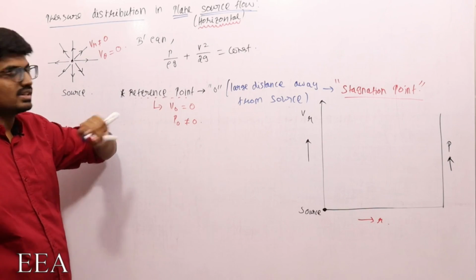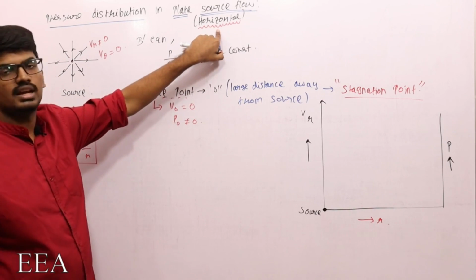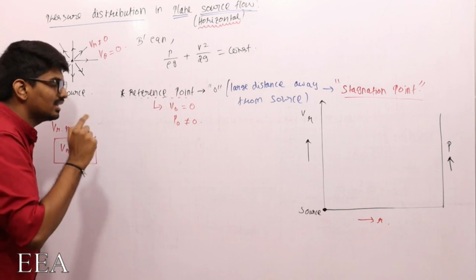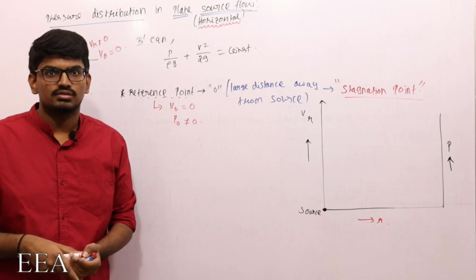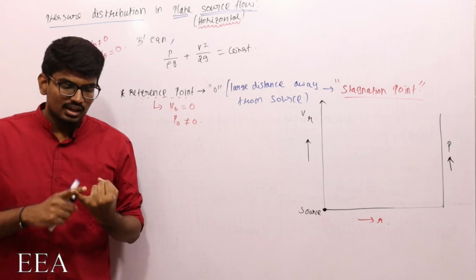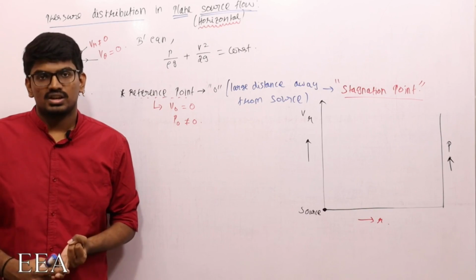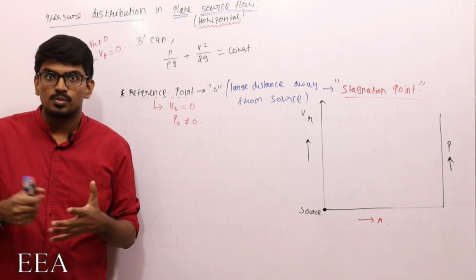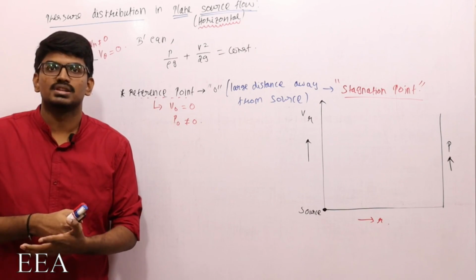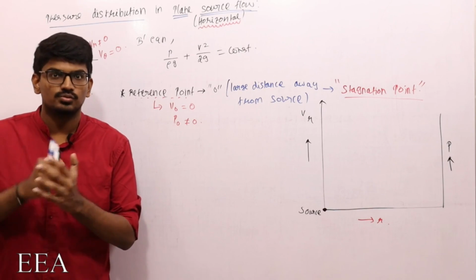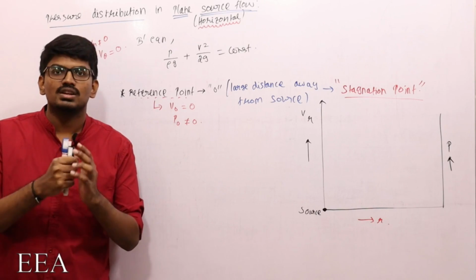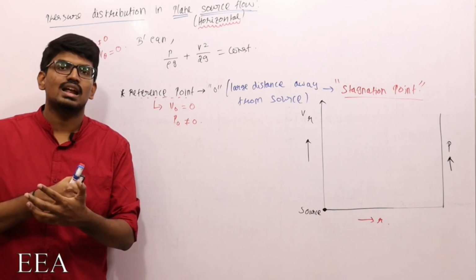Now, this is our general Bernoulli's equation. I'm not considering the potential energy because it's horizontal, and the potential energy will remain the same along a horizontal line. We also know that it is an irrotational flow. Why is it an irrotational flow? All the flows which we are considering from the beginning, I already said that if the stream function and velocity potential function both have to exist for some particular flow, then the flow should be irrotational and incompressible. I said this at the beginning itself when I was discussing uniform flow.